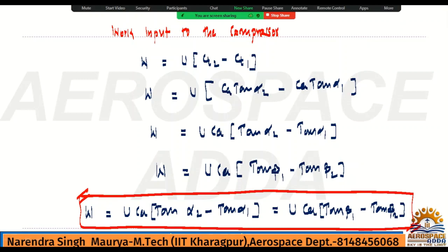Because there is the formation of a boundary layer inside the duct where the flow is going on. So the boundary layer formation will be there in reality. So you will have less area, the area will be decreasing because of the boundary layer formation. For that reason, to compensate for that reduction in work absorbing capacity, the stage is taken into account by a factor known as the work done factor.